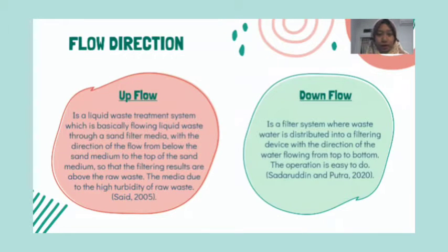Next, flow direction. There are two: upflow and downflow. Upflow is a liquid waste treatment system which basically flows liquid waste through a sand filter media with the direction of flow from below the sand medium to the top of the sand medium, so that the filtering results are above the raw waste and the media, due to the high turbidity of raw waste.